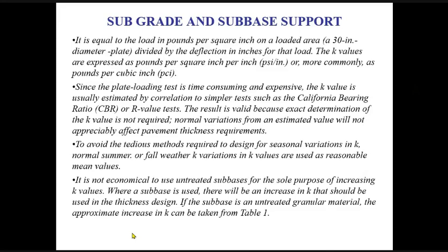Another thing is, we don't use untreated subbase for the sole purpose of increasing K values. Where a subbase is used, there will be an increase in K that should be used in thickness design. And if the subbase is untreated granular material, the approximate increase can be taken from this table, that is Table 1. Let me show you the table.